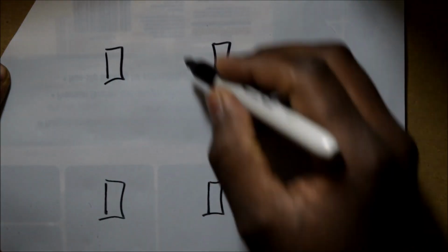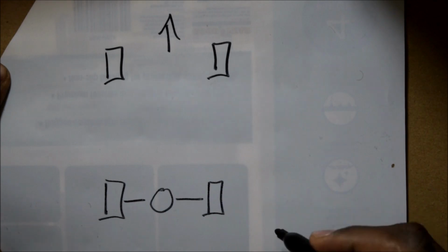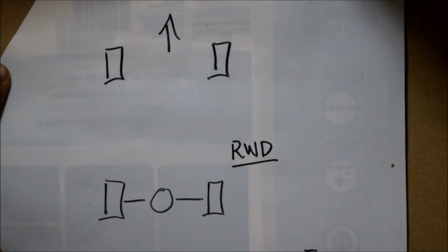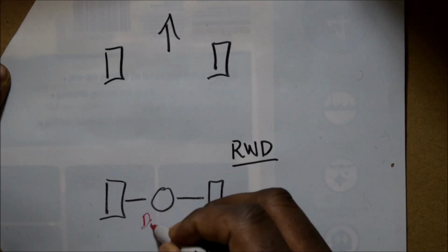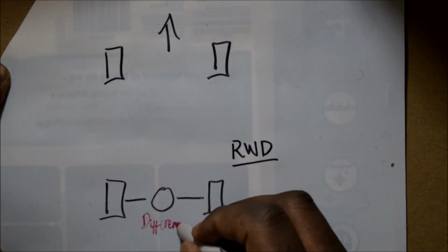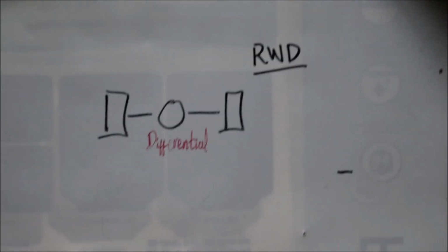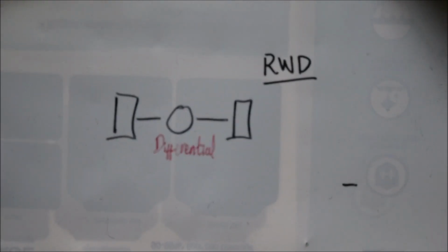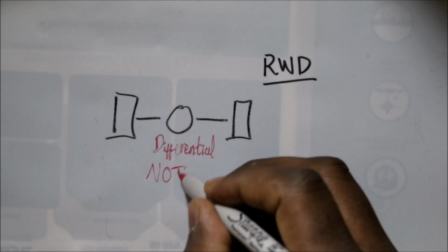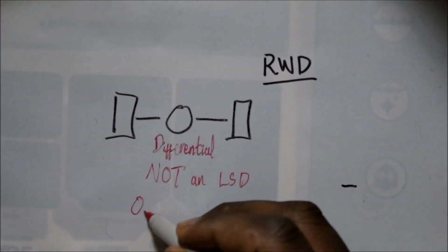Allow me to break some hearts for a minute here. We got a rear-wheel drive Infiniti sedan, for example, and so you have a pumpkin in the rear that transmits power through those axles to the rear wheels. That's called a differential. Unfortunately, or by some design, since 2002, the flagship sedans have not had any form of limited slip, no viscous LSD or anything like that. So they are open diffs, right?